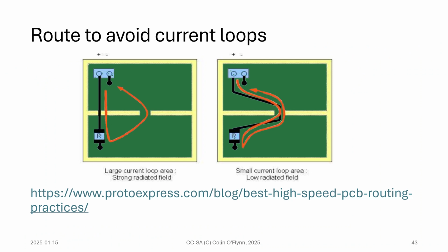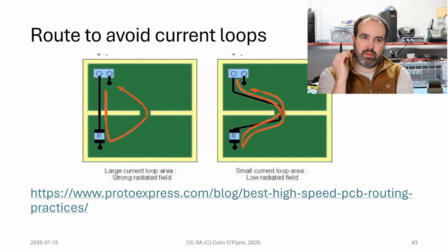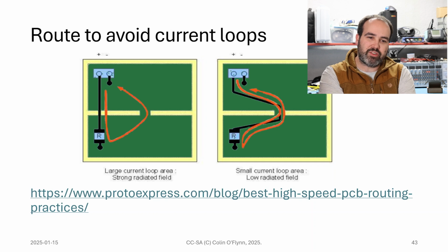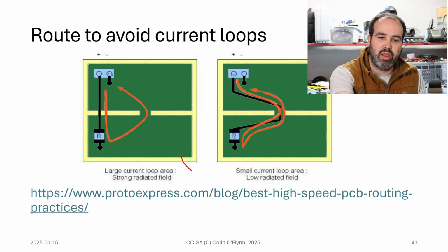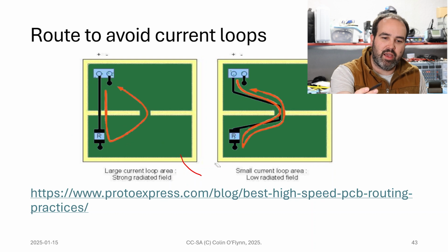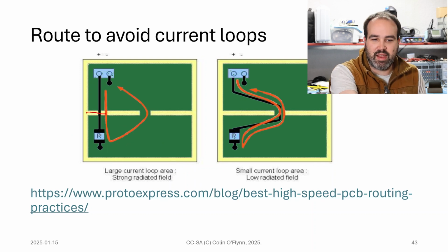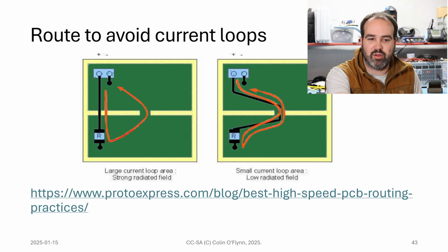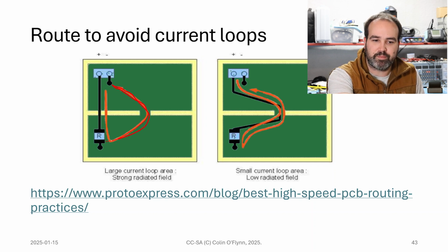So I mentioned that I was going to talk about power planes and things like that. So very briefly, I'm not giving a huge overview of good routing and everything like that, but I will mention this pretty common problem, especially with the 2-layer board, where I've got a big ground copper area. What's pretty common is, say I had some other traces in here, which meant I have to have effectively this slot, right? So I have this slot in my ground.